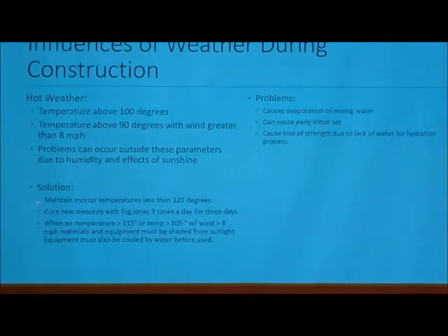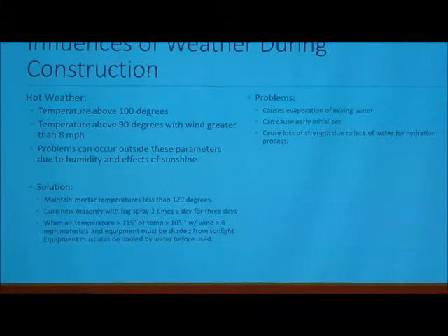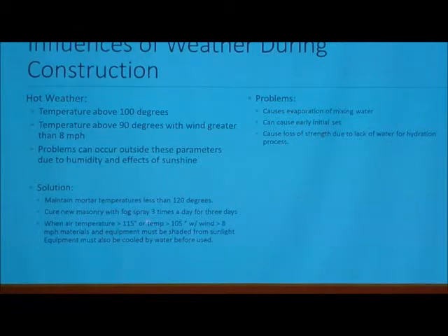You must maintain a water temperature less than 120 degrees, and once the masonry is laid, you have to fog spray it 3 times a day for at least 3 days if the temperature is that high. When it's greater than 115 degrees, or 105 with an 8 mile an hour wind, then you must use equipment to shade the brick from direct sunlight.